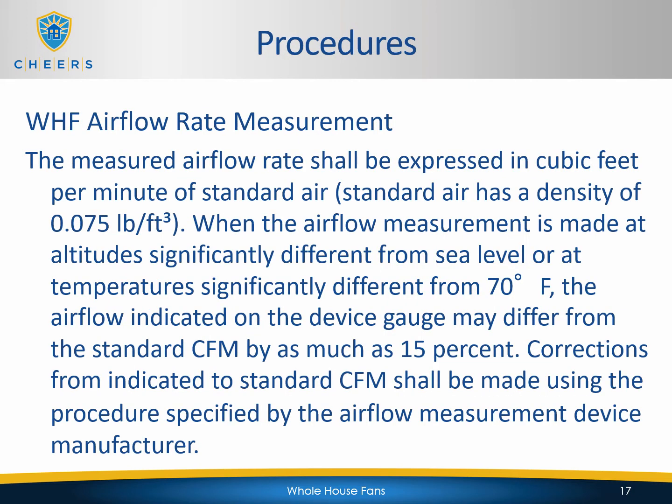Okay, so now let's get into the actual procedures, how we perform these verifications. How do we measure the airflow? How do we measure the fan watt draw? Let's take a look at that. Let's start off with the whole house fan airflow rate measurements. The measured airflow rate shall be expressed in cubic feet per minute, or CFM, of standard air, and standard air has a density of 0.075 pounds per cubic foot.